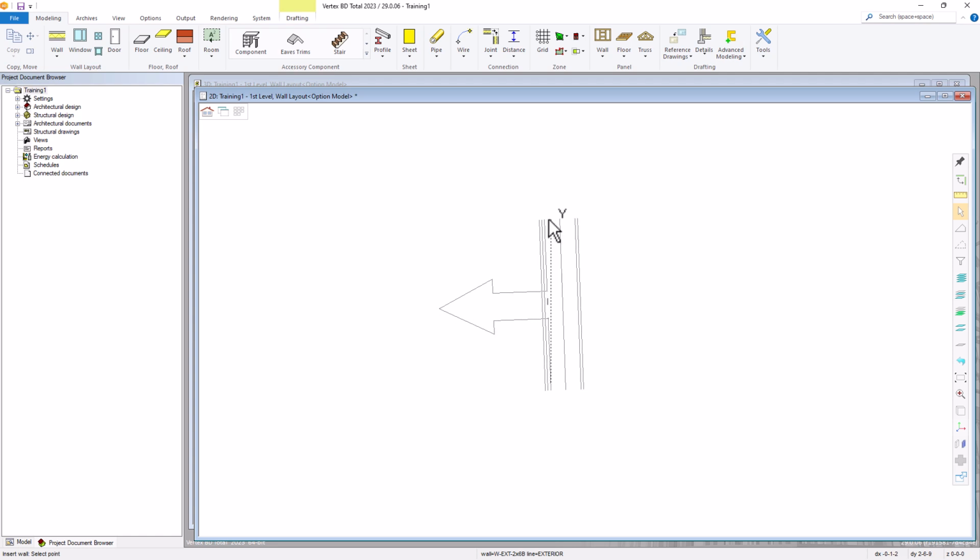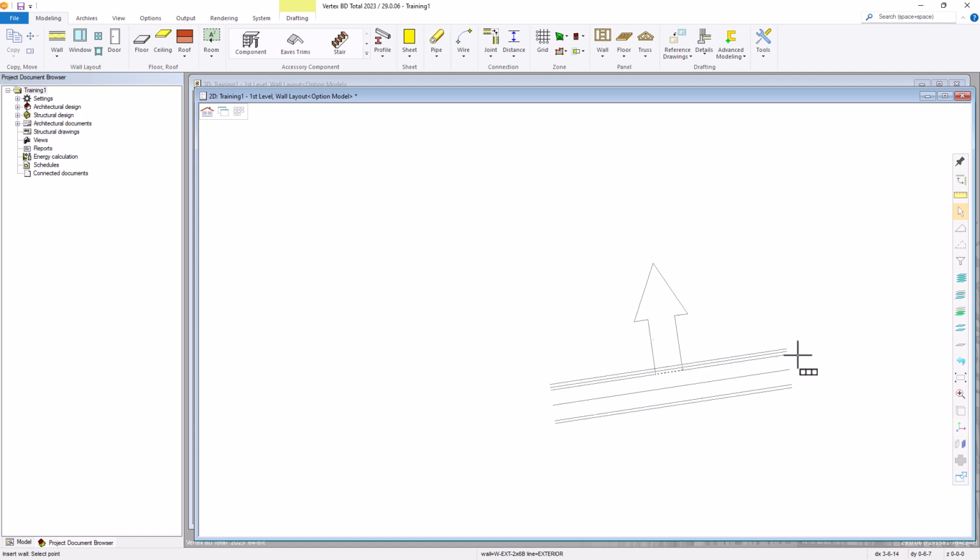That's activated by clicking the left mouse button. So if I click the left mouse button while I see the constraint on the screen, it locks it. I'm going to do the same thing for the horizontal. If I left click while I see the X constraint, now it locks it. And then for the Y, or for the 45.